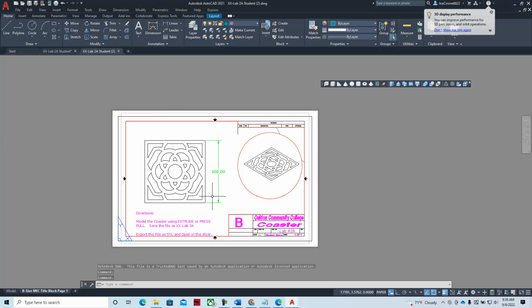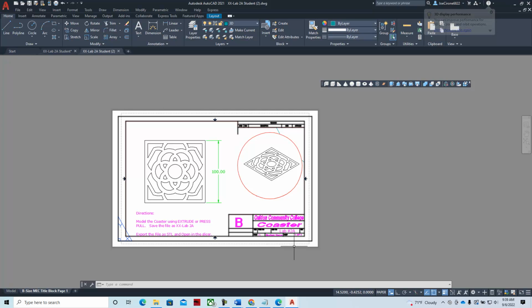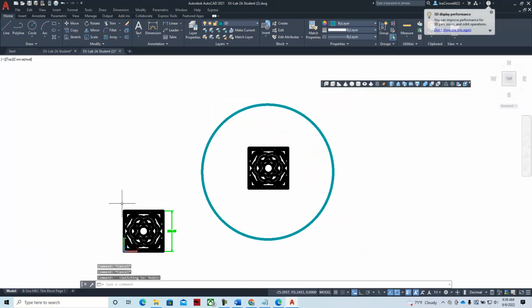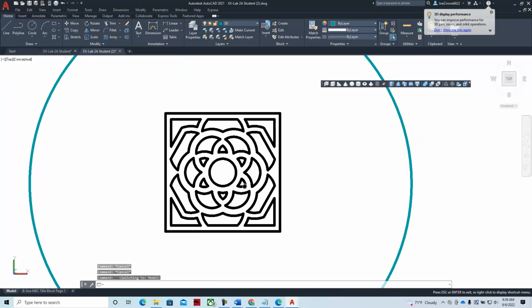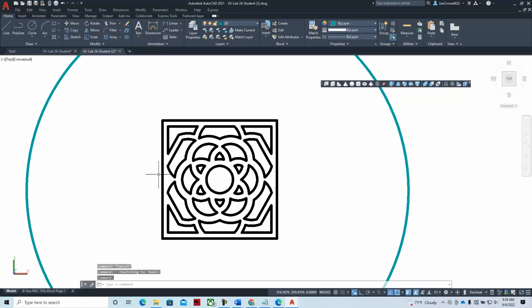And so here's what it looks like with AutoCAD. Basically this is a title block that we will fill out and put our name on. And then we're going to model this over here by clicking on this model tab using AutoCAD. If I turn the wheel on the mouse and push the wheel on the mouse, I can pan and zoom.